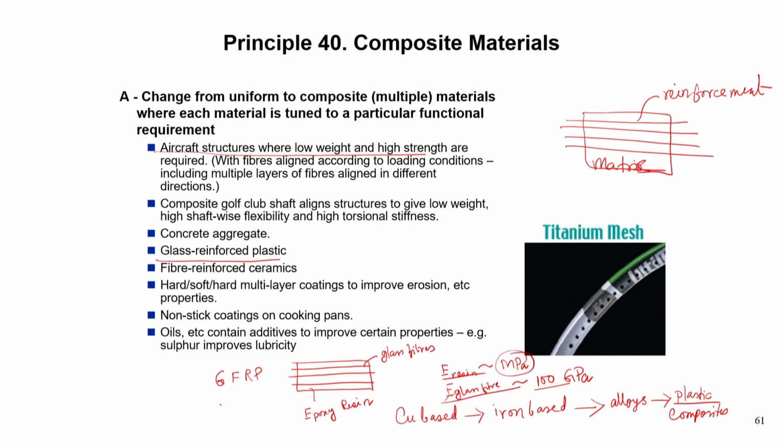You will get a modulus of elasticity E of a GFRP which will be as good as aluminum alloy, something like 50 gigapascal. That is an advantage, because if you compare the density, you will see that it will be at least 1/3 lighter in comparison to aluminum alloy. So that is a huge weight advantage.